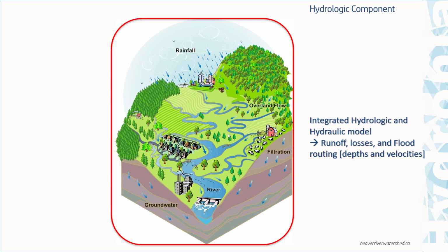And that surface runoff component, a HydroBID flood model is going to use that to route this surface runoff component through the basin and also through the drainage network of the basin. Considering the problem related with the flooding in the urban area, using this kind of modeling, we can analyze this in detail, defining the depth of the water and also the velocity, the vector velocity.